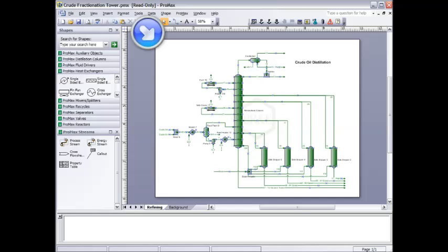This is where the flow diagram of the system is drawn and the easiest place to make specifications and changes to the unit. To the side and bottom of the screen are scroll bars that will allow you to move the visible flow page up, down, left, or right. Below this is a section that right now is completely blank. This is the message log area and will show information about the simulation, including all messages about how an execution of the project is progressing and any errors or warnings that are being generated by the simulation.